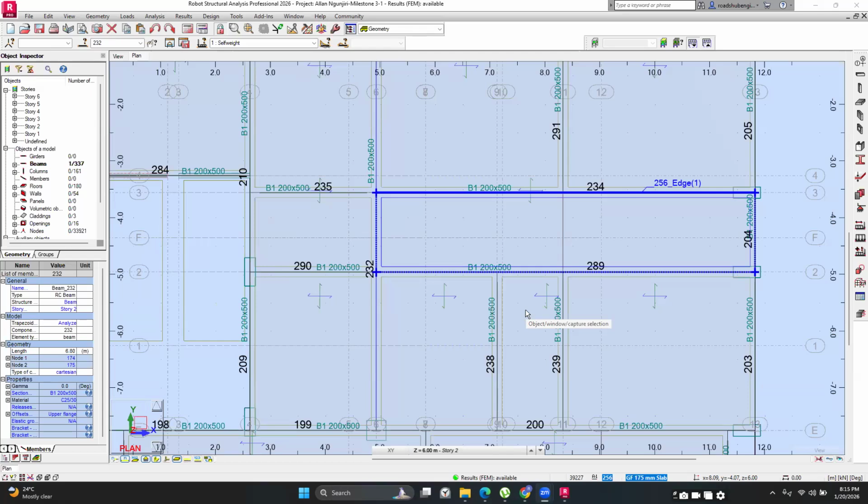Slender columns are easier to bend, or easier to fail through buckling. Short columns are majorly going to fail through compression or punching through the midsection of the columns. So that's one of the things you may have to consider when designing your columns.